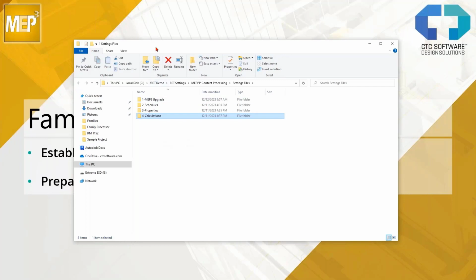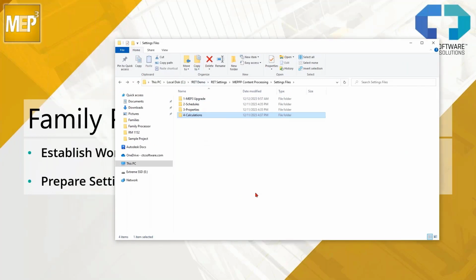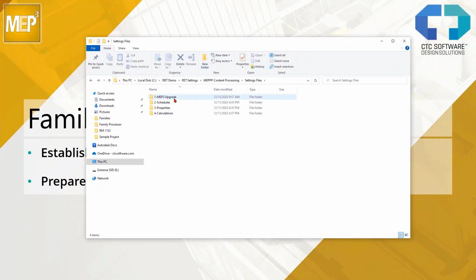The second piece to this is preparing the settings files themselves. Now, each family processor settings file is mapped to the shared parameter file in our working environment, not yours. So those need to be updated. If you don't update those, when you open family processor and you load the settings in, they will not be 100% correct. Some data is going to be missing. So you have to do this to make sure that things work smoothly.